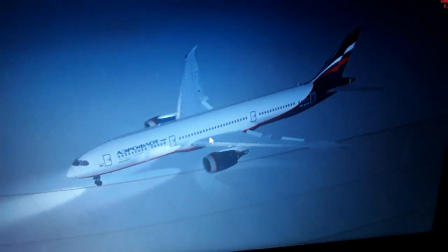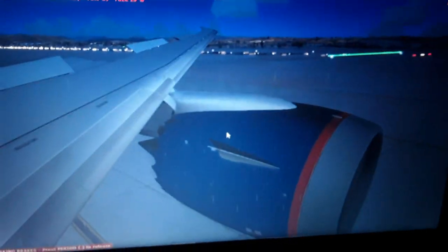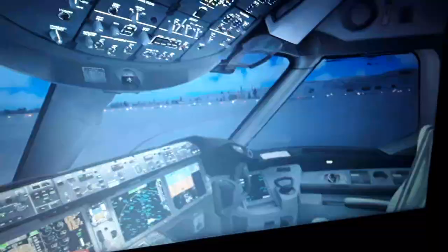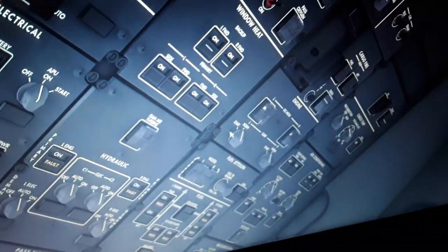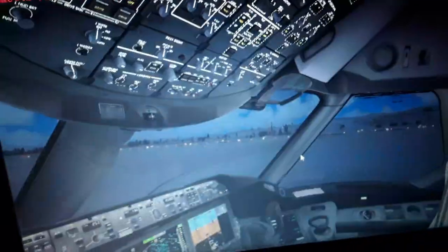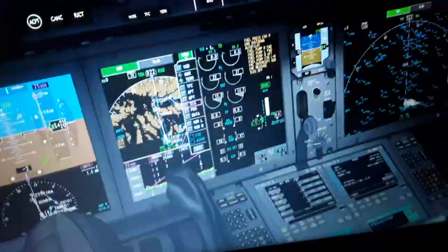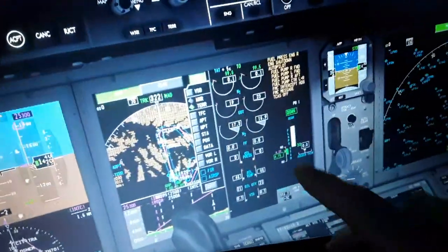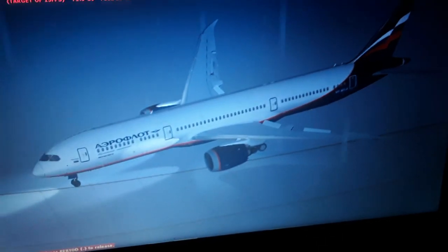We need to restart very quickly the engines of the Boeing. So we go over here, the overhead panel, start the auto start, both on. You will see yellow reconfigurations in the overhead. So you see now we have pressurizer from the APU. It's gonna accelerate the engines, pressurize the engine starter. So you can see here the roaring of the engines.